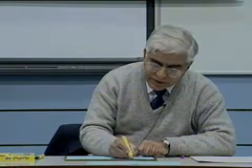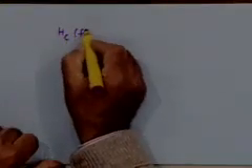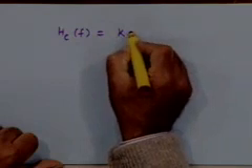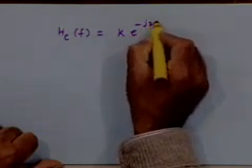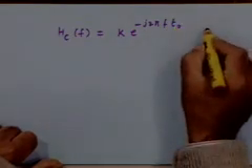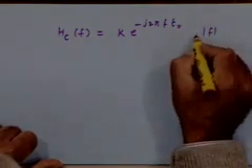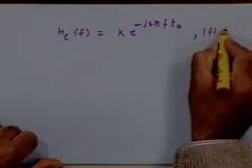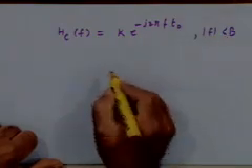So we could then say that the ideal channel transfer function, instead of qualifying unconditionally as being equal to k e to the power minus j 2 pi f t0, we will say that this should be so for mod of f less than b.